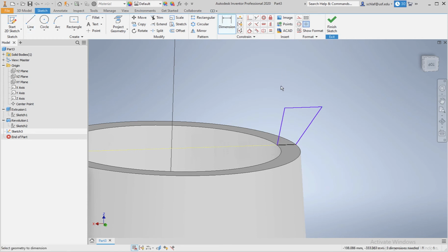So this is our next shape that we want to extrude, but of course we need to dimension it first. The first thing, and the most important constraint here, is to define the angle, because this will jut out from this tower, and when you print something like this, you cannot go much flatter than 50 degrees or so, especially when the object is round. So I'm just going to give this 55. I hope this will print well, and let's go with that. Now we also need to define the height again. So let's make this 4 millimeters.